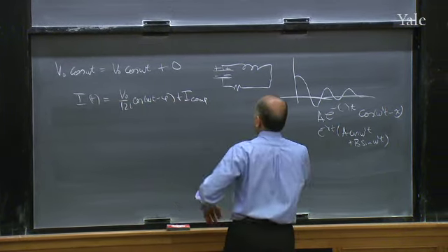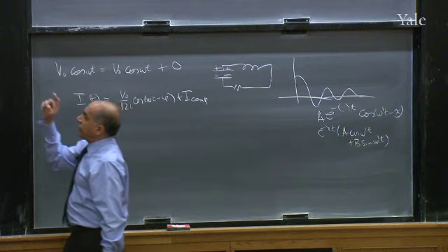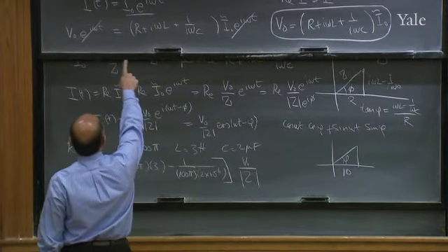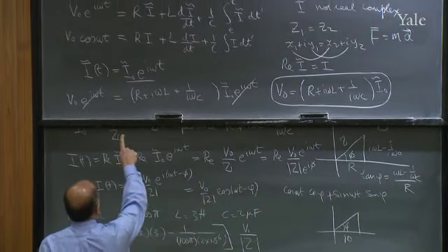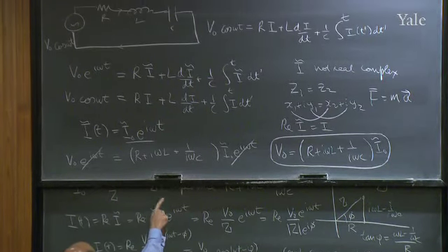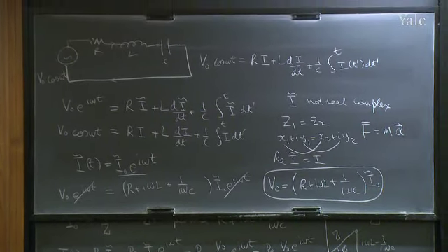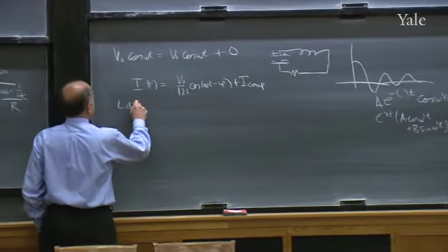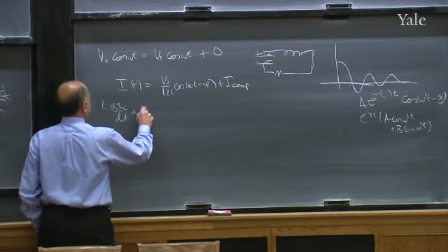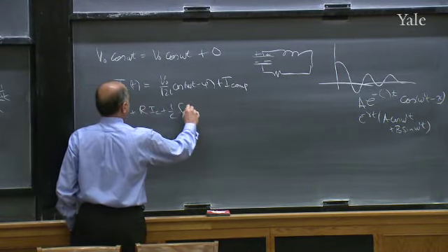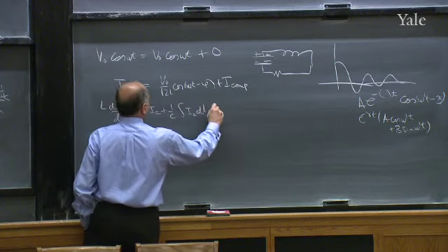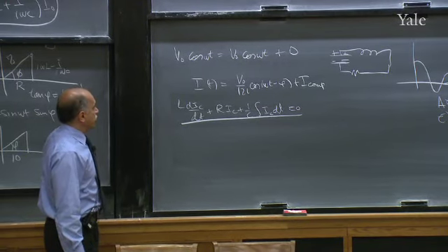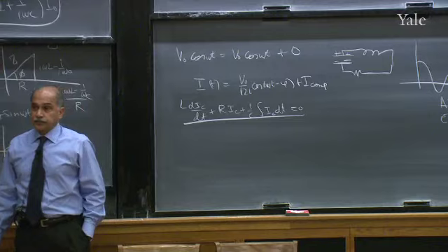Because if you take this complementary function and add it to the equation, you might think it will mess up the equation, but it won't. Because the I that I wrote down will give me V naught cos omega t. The complementary function, when you take R I plus L dI/dt plus 1 over C integral of I dt for the complementary part, you will get 0. Because the complementary guy obeys the following equation: L dI_C/dt plus R times I_C plus 1 over C integral I_C dt is 0. The equation satisfied in that loop. If it has a non-zero solution, you can add it to your equation.